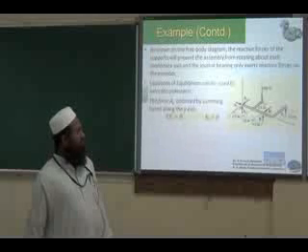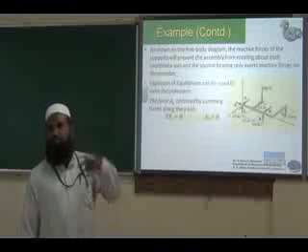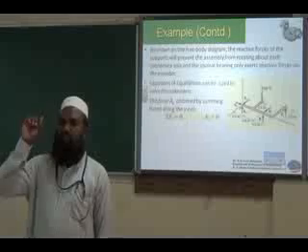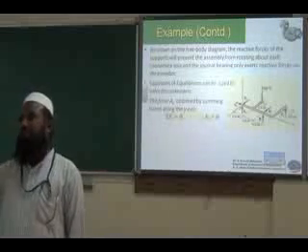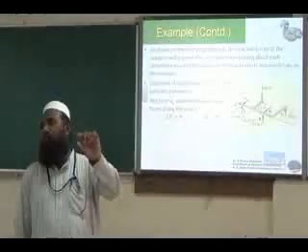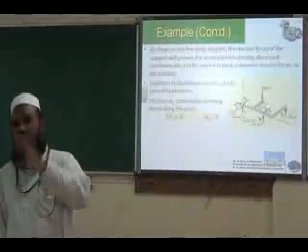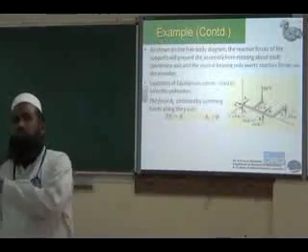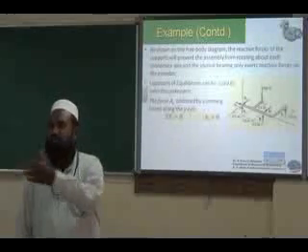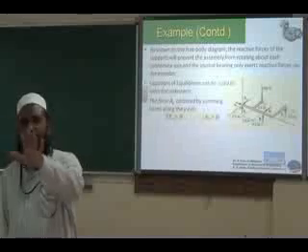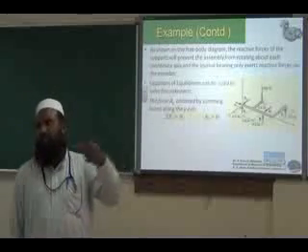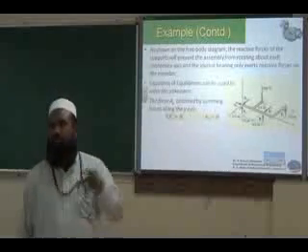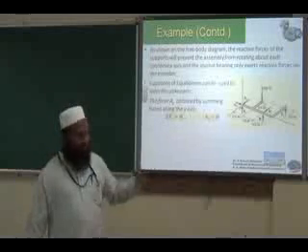Now we have to find the other forces. So to find the other forces, we use the moment equation. If you remember in our 2D problems, first we use sigma Fx equation if there is an x reaction, and we find the x reaction. After that, we use moment equations and if needed, force equations also: sigma Ma equals 0, sigma Mb equals 0, then sigma Fy equals 0. The same applies here. Since there is only one Ay, we first use sigma Fy equals 0, and we found that Ay is equal to 0 since there is no other force.